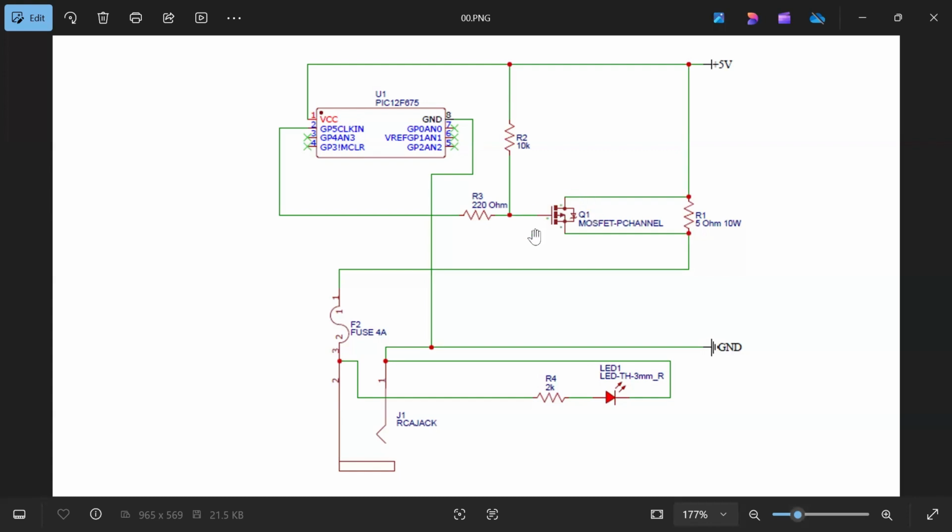So if you're using a MOSFET, that's one of the things you need to really care for and calculate, that resistor value. And that's a real oversimplification of MOSFETs. There are a lot more details that need to be cared for when you use them. The P-channel MOSFET is a little bit easier to use and has a lower hurdle for requirements than the N-channel does. Okay, so that's a lot of detail on the MOSFET. That's probably the most interesting thing in here.